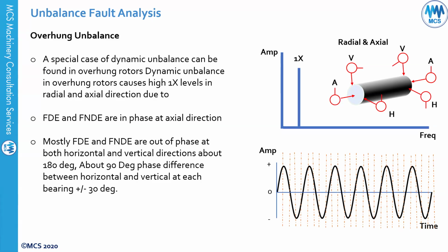Imbalance is the force and the measured vibration is the response, and this forcing frequency can affect your structure and cause this structure looseness. And if you reduce the vibration of the forcing frequency, which is the imbalance, this will definitely reduce the effect of the forcing frequency on the structure, and it will reduce the vibration causing the structure looseness as well. So by balancing the machine, this could be a solution to solve structure looseness problems.